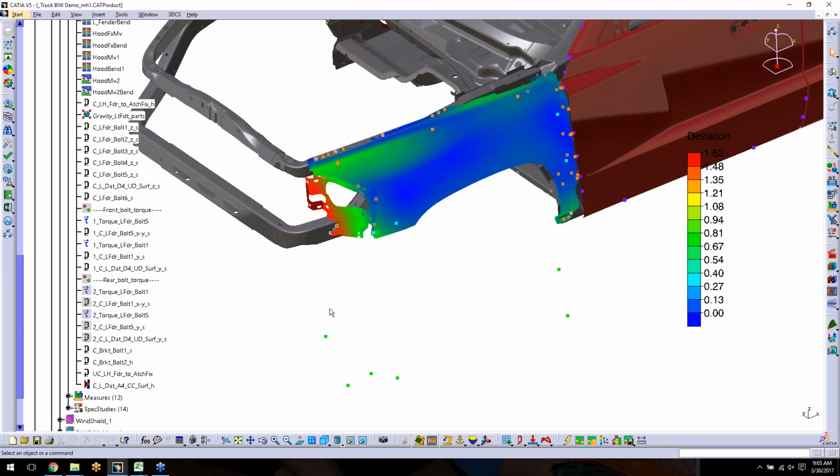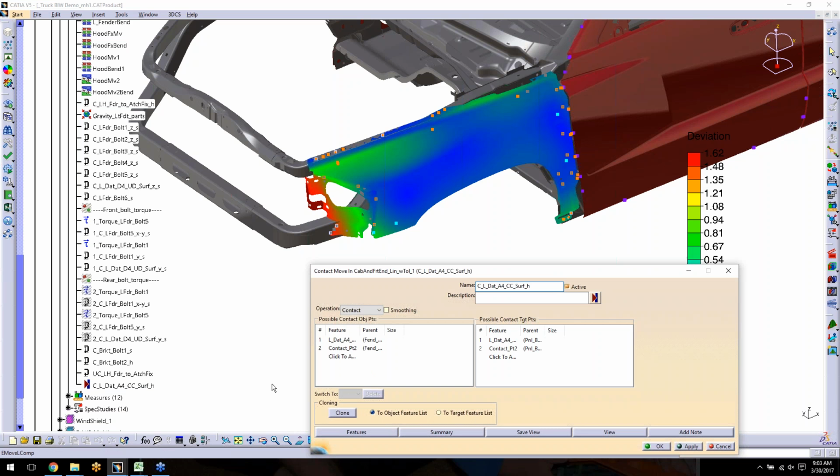Does the contact move consider several contacts simultaneously? This was something that we didn't have before. One of the scenarios that you showed, Maria, was doing 5 joins at the same time, 5 welds simultaneously, and that was on the aircraft skin model. And we can account for all of those moves at the same time. So you can have multiple contact or join moves simultaneously.